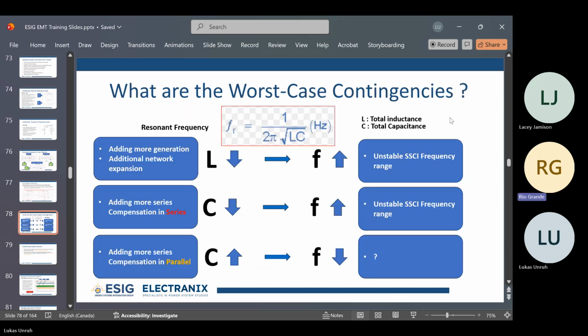So we can do some just some impedance-based thinking about the effect of various network configurations on the resonance that we're looking at. We know our resonant frequency is going to be a function of the inductance and the capacitance in the system, pretty much like this: 1/√(L·C). And so when we think about the inductance of the system, when we decrease the inductance, this actually increases the frequency.